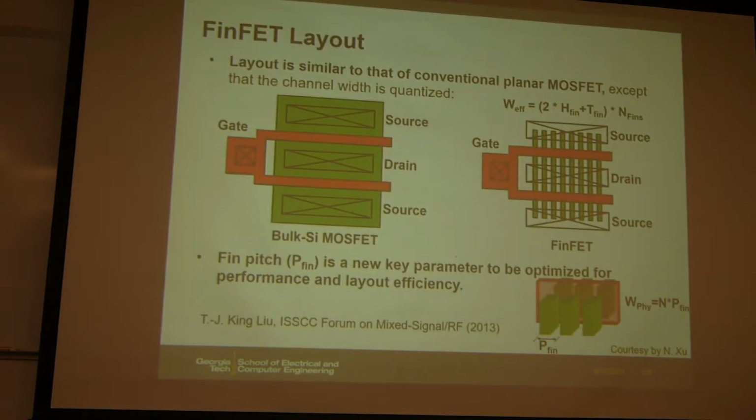And then I just want to talk about the differences. Let's say for a circuit designer, if you're not a device engineer, what do you need to pay attention to if you are designing the circuit with FinFET instead of planar transistor? So the biggest change here is the W now is quantized. Why is that? Any idea?